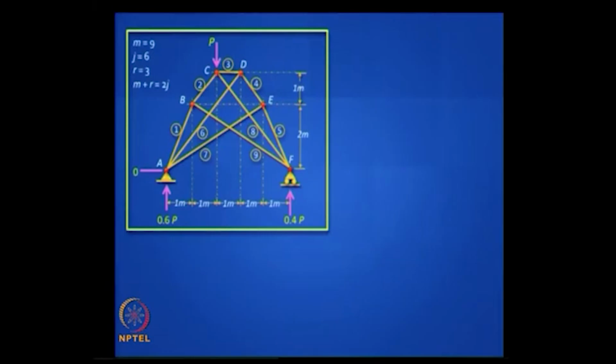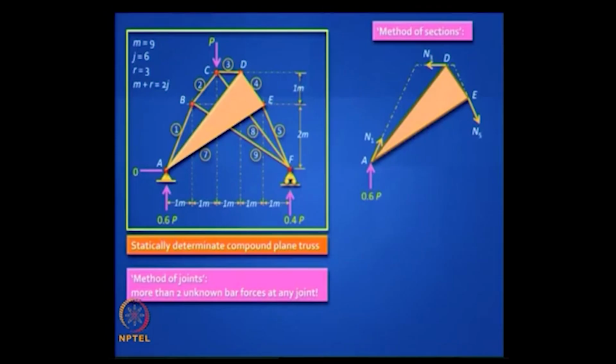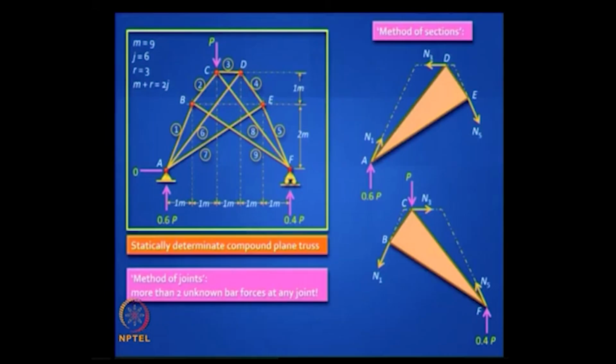This is again a compound truss but statically determinate. What you can do is view that segment as a triangle and separate out that triangle, which means using a pair of mental scissors and snipping through those connecting bars, you expose those bars, and here you have, one look at this picture and you know that there are only 3 unknown forces, you have 3 equations of equilibrium available, you can solve for it. Or you could take the other triangle and you could solve for it, and once you have got the idea it is easy to calculate because you can use any 3 equations and solve it.